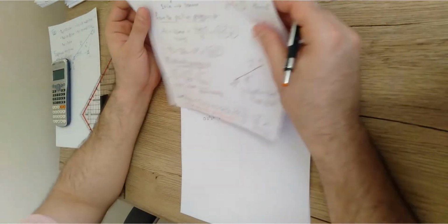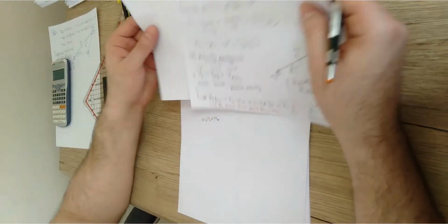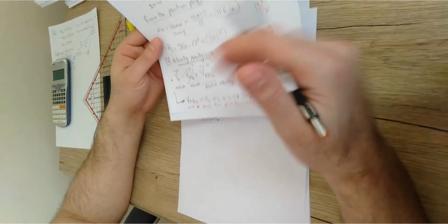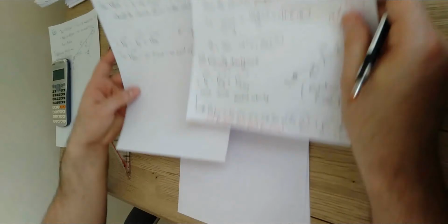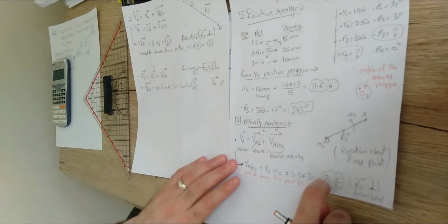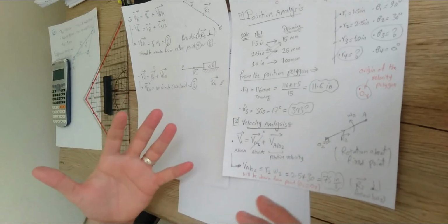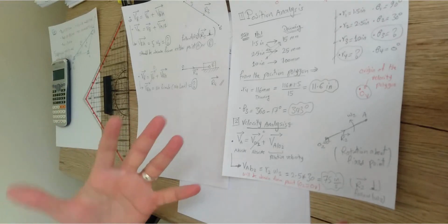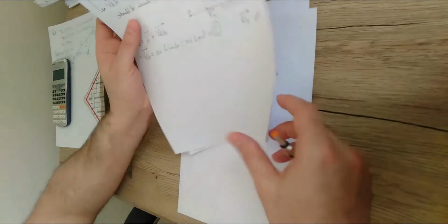So the question is, before we even draw, should we do a scale? In most cases you're going to do scaling for the velocity part. As you can see, we have only one value here, which is 75 inches, and 75 inches is a big number. How about if I decided to draw this 75 inches as 50 millimeters, for example? So I'm going to do a scale here.